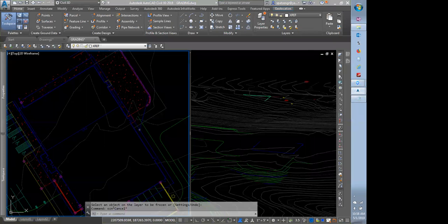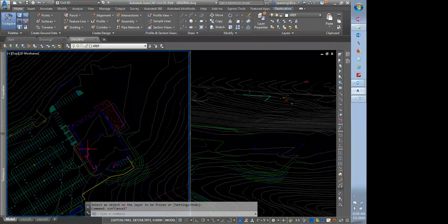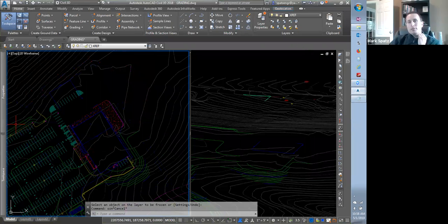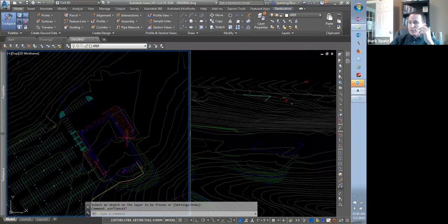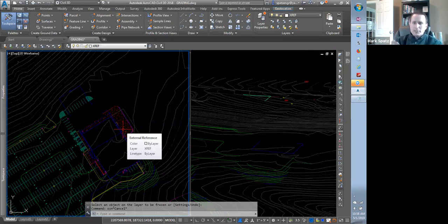Okay. So, is this going to work? Oh, there we go. Okay, so with that alignment stuff aside, with that clarification there, for commercial site grading, what we really want to be focused on is coming off the building. So in many cases, you have to pick a first floor elevation to start with, right? And then you can change it later.